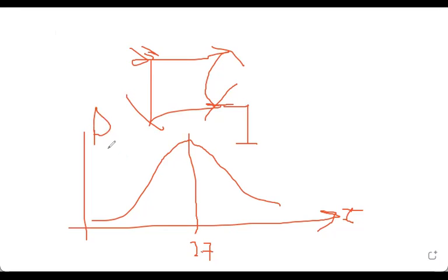So the higher the intensity, the higher the power you are collecting from your solar cell, till we reach what's called 2.7 sun. At this point, your power will decrease.